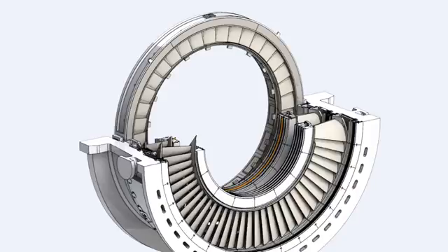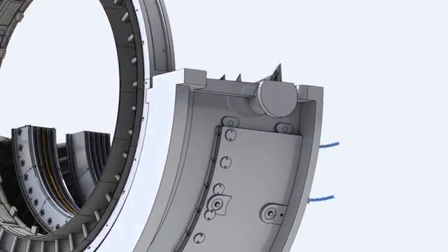the nozzles. The turbine shell function is to control the radial and axial positions of the shrouds and the nozzles, and the relative clearances between the nozzles and the rotating buckets. The position of these parts is critical to the turbine performance. The lower half features 2 trunnions used with other trunnions on the forward compressor casing to lift the gas turbine to or off the turbine base. The external surface of the turbine shell incorporates cooling passages.